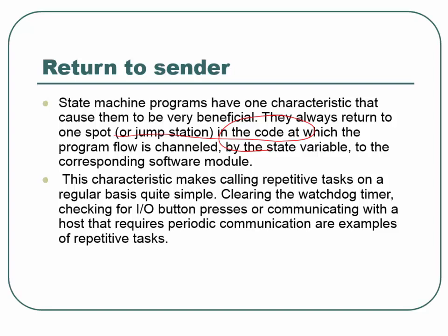When we turn on our washing machine, it has a reset state. Our reset is idle. Now idle, we haven't defined. You may want to have the drain motor, for example, turned on, or the valve open. So if you turn the machine off and turn it back on, and there's water in the machine, you want it to drain. You think about that, but that's much later. At this stage of the game, all you define is our idle. We always go back to idle.